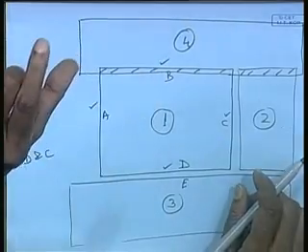The worst is when I put panel number 4 and there is a big gap between panel 1 and panel 4, you are helpless. Putting a small strip there will be a terrible job. Instead, I have it overlapping and then cut off the excess material. That is easier. Well, that is the practice.